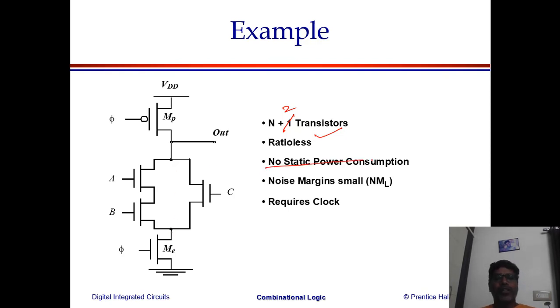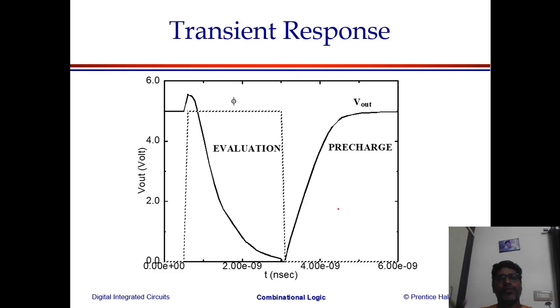No static power consumption. That's the beauty of this. You have actually removed the problem that exists with the ratioed logic, right? There is no static power consumption. The noise margin is small, and it requires a clock. These are some of the difficulties. It requires a clock, which means the clock again consumes power, right? All these are entering into complications.